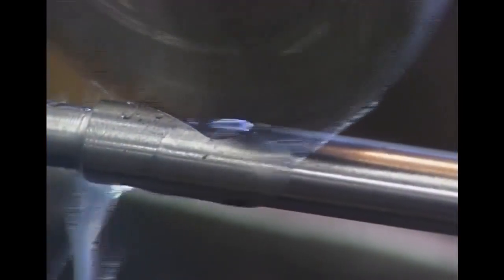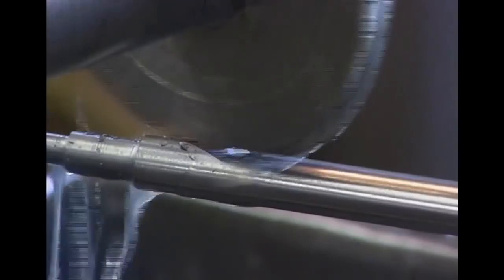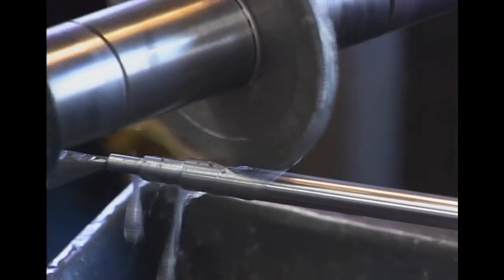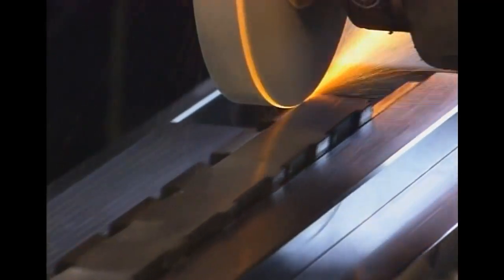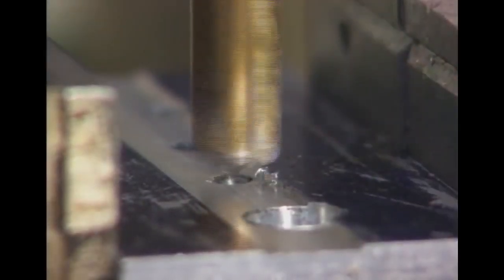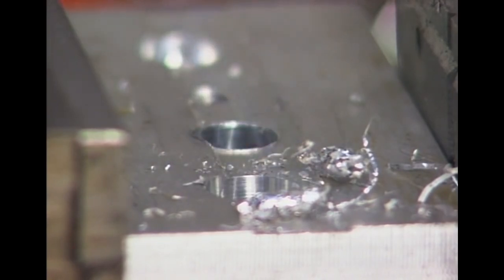Since the 1960s, a form of high-speed steel called powder metallurgy high-speed steel has allowed tools such as drills, milling cutters, and form tools to be made to near-net shapes that offer superior grindability. The use of coatings, particularly titanium nitride, allows high-speed steel tools to cut faster and last longer. Titanium nitride provides a high surface hardness, is resistant to corrosion, and minimizes friction.